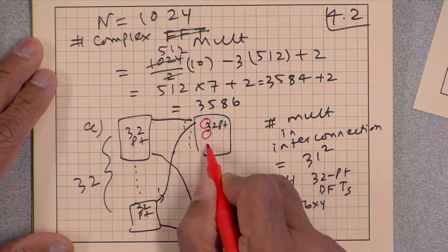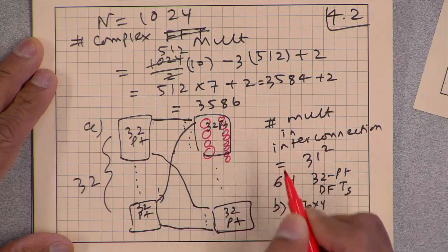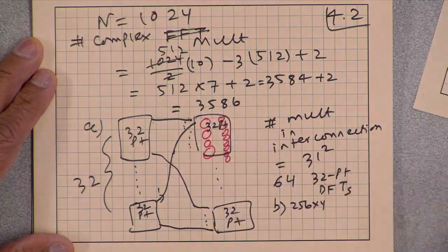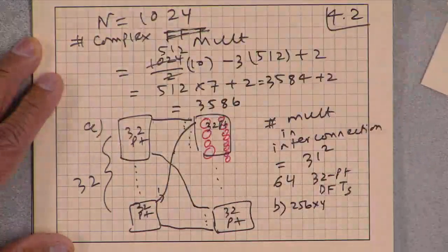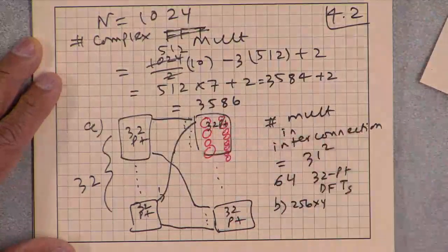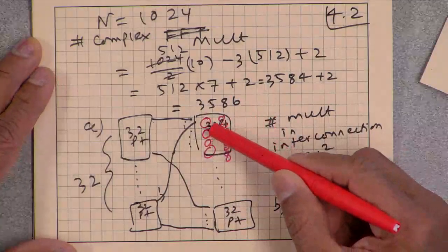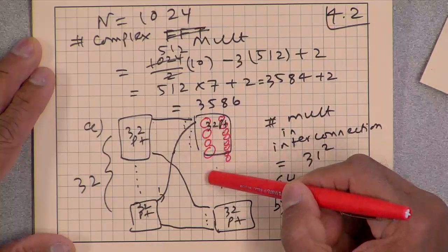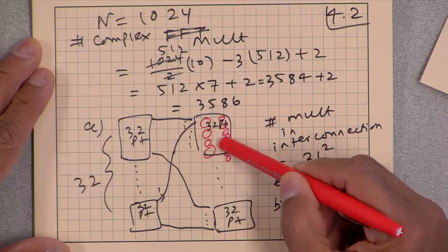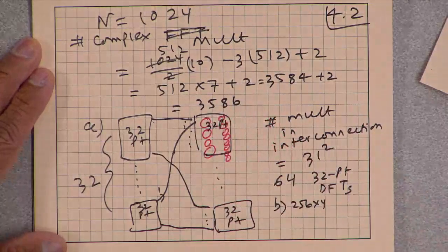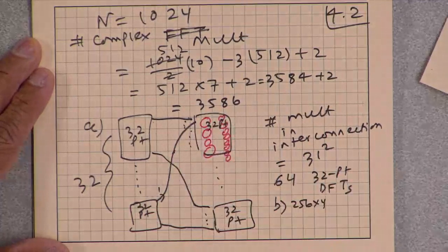So in a way, think that these 32 points are not DIT or DIF, and you can't use that formula, but rather think about each of these containing 4 8 point, and 8 4 point, and the interconnections. So that's why there is that bracket, and that means all of these 32 are replaced by this kind of thing. Is that making sense now?